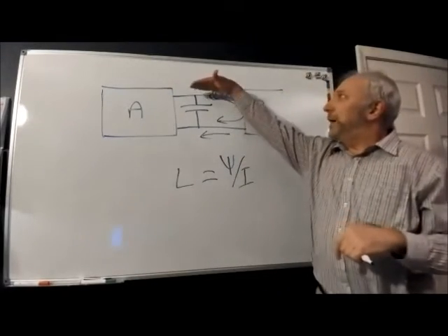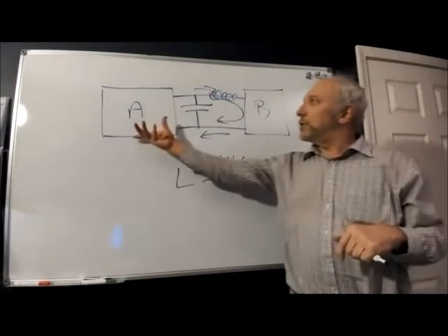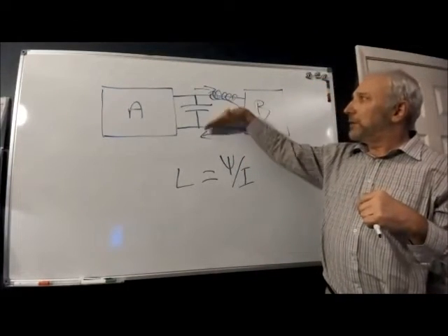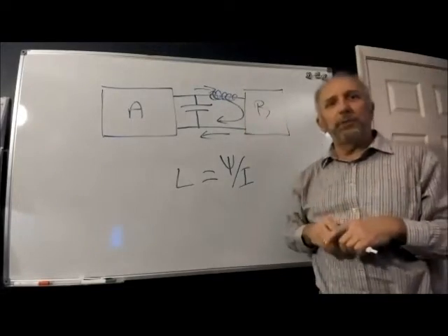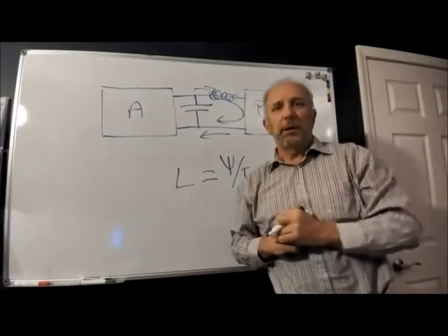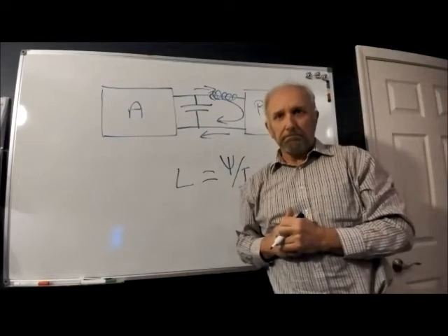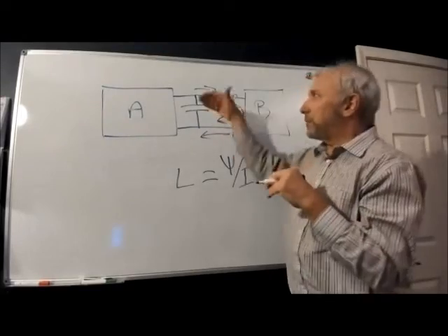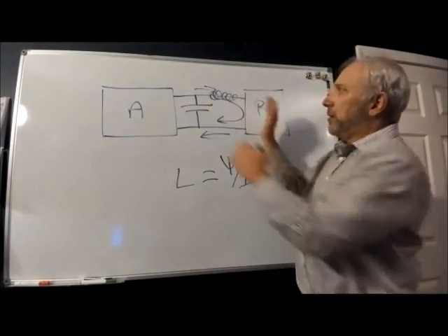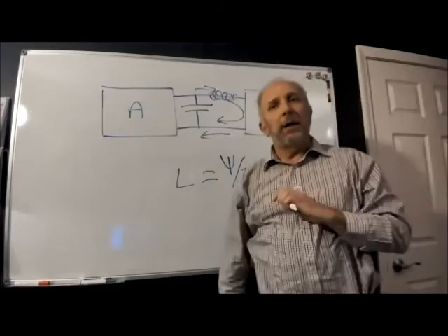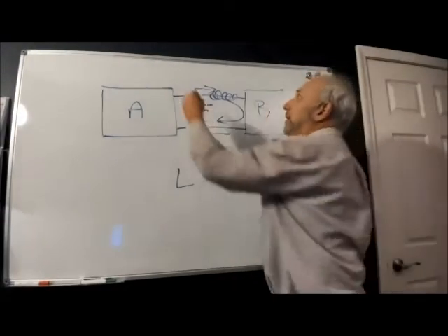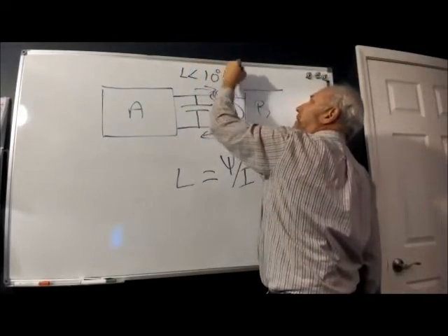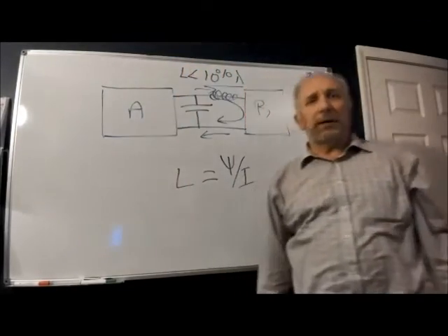Interesting. So we have two conductors, and the intention was to send a signal or power from point A to point B. We now have conductors separated by dielectric. It also forms a loop. We have something called a lumped equivalent circuit model. A lumped model talks about the overall capacitance between here and here, and the overall inductance in this loop. This is when L is less than about 10% of lambda. There's lambda, we just talked about that a little bit ago.